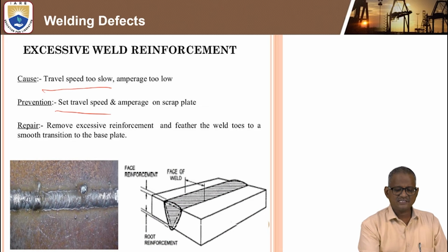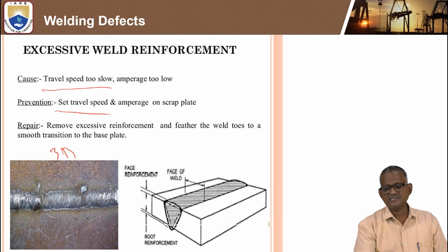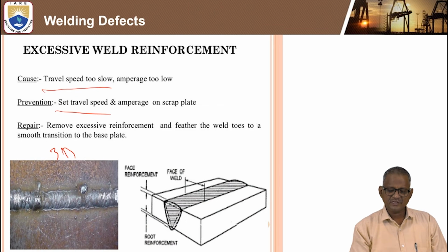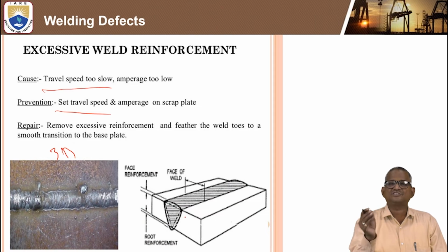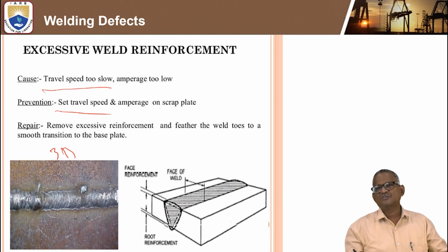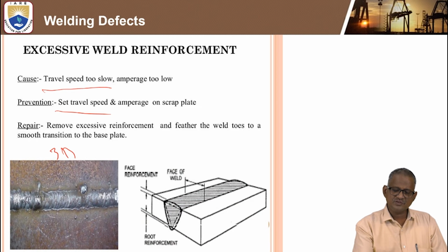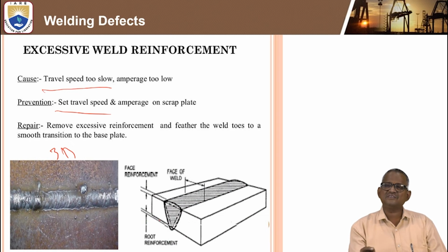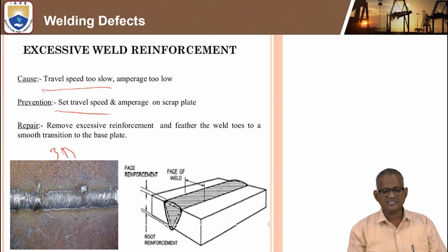Okay, so you can see this is a 3D figure for this excessive weld reinforcement, and we can see the 2D isometric view of this weld reinforcement. You can see clearly the root, how much distance you required, it will enlarge, which leads to more reinforcement. Sometimes even when you want to do some application, it cannot break. Even though it is a permanent joint, in some cases it overflows, which cannot be eliminated, even by a chipping hammer. So that is another drawback.